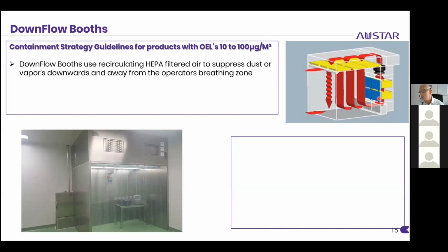So fine dust filtration, HEPA filtration, so that by the time it gets to the fan, all the dust has been removed, and then we can deliver it. We can almost create an aseptic environment inside there by delivering through terminal HEPA filters. To make it work, we push a little bit of air out of the system, so we get a nice refresh rate inside there, which naturally is drawn back in again.